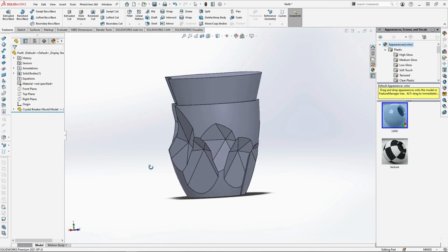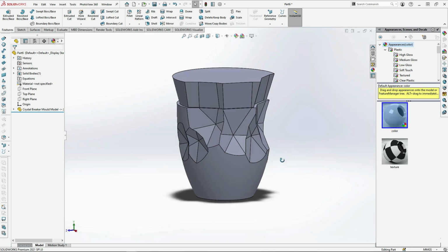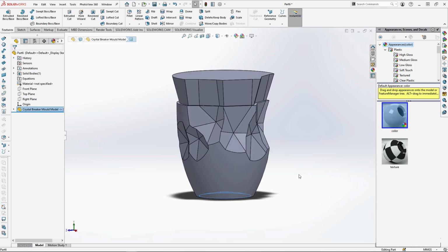The model is made up of the beaker design here, with the top part being a spare. This is used for slip casting clay into the mould. As slip dries onto the plaster walls of a mould, the clay level drops. Without a spare, the top part of the casting would be thinner than the rest. So to cast it evenly, a spare is essential in plaster moulds. This design also has a foot ring, so a bottom mould piece will be needed.